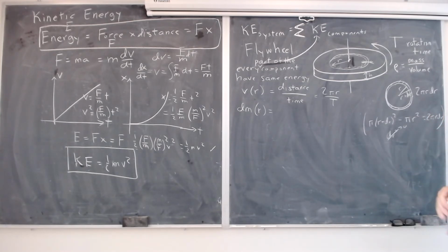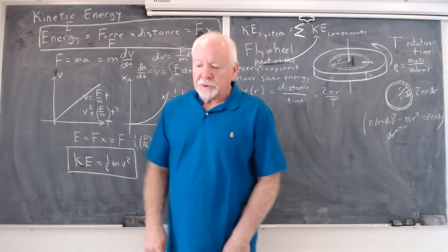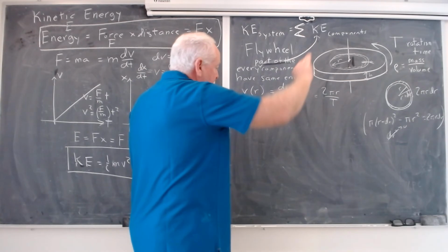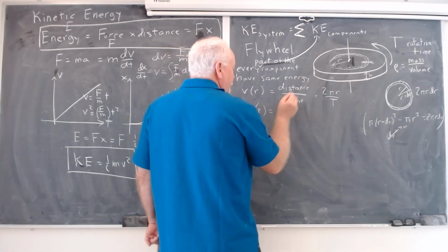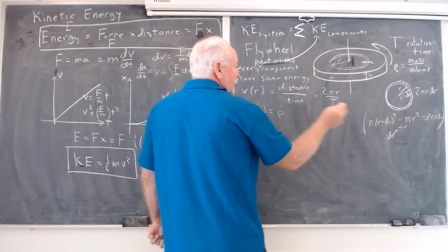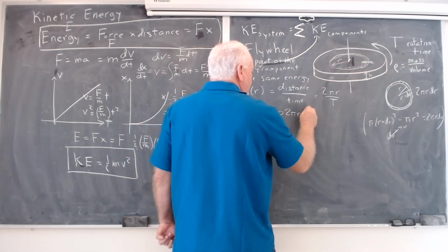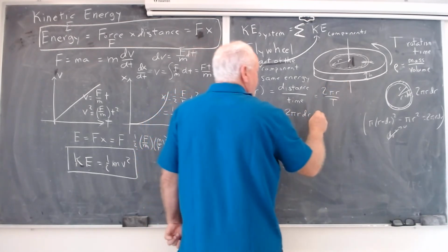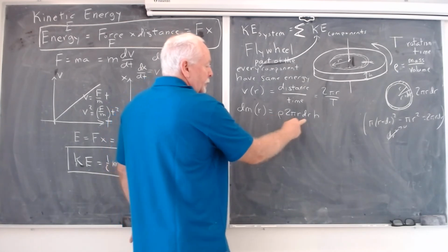So however you need to do it. The mass of my differential element, the cylindrical shell there, is equal to rho, the mass density, times this area, 2 pi r dr, times h, the height. Density times volume.